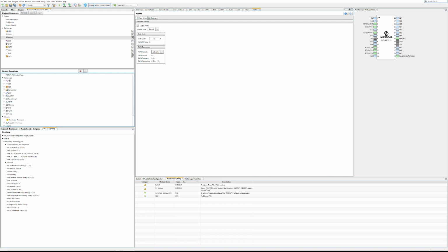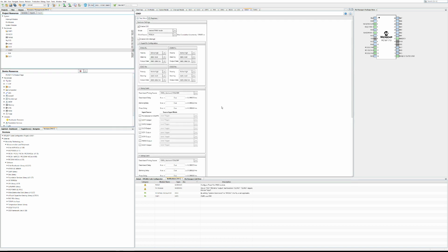So you can define a PWM output here and then use a complementary output generator to give you an opposing output with optional deadband or phase delay or a variety of other things.